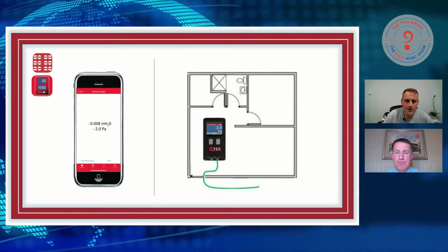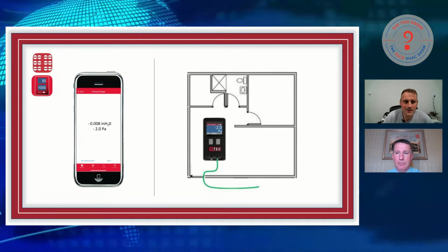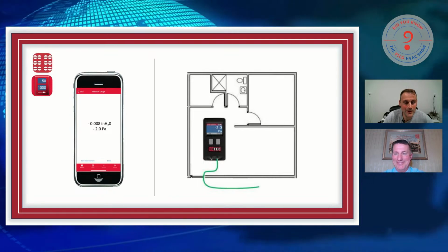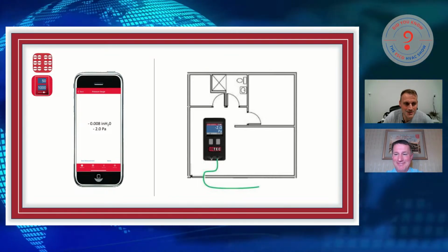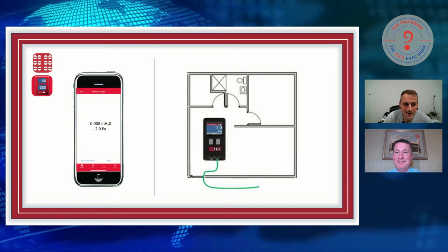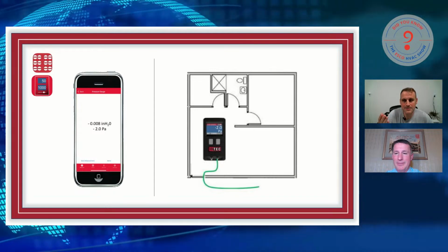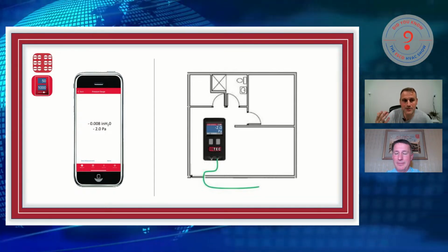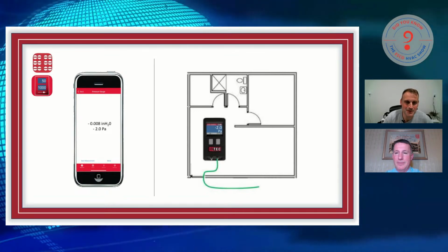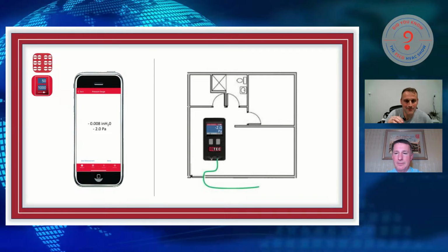That's right. You can run a tube outside the door on a non-windy day, and you can see that ductwork is leaking. We call that a dominant duct leakage test. Well, I like to call it a dominant duct leakage screening. I call it a screening because it's not foolproof, meaning you could get a measurement and think that you don't have a problem when you do. But you could also get a measurement that tells you do have a problem and it's trustworthy. There's a lot of talk that goes into that, and at some point, I probably need to make a video on it.